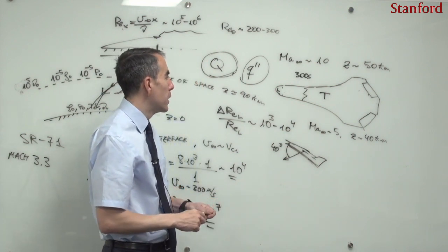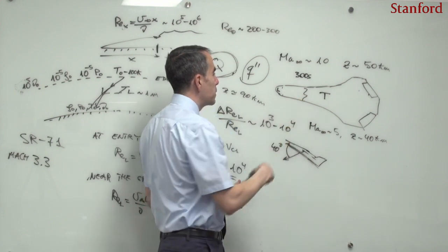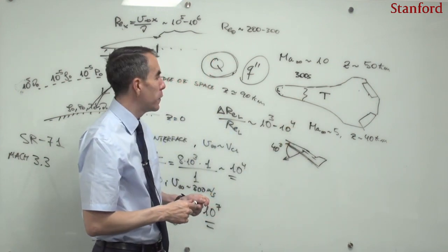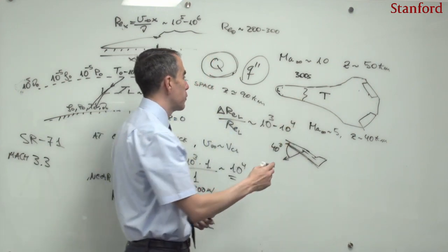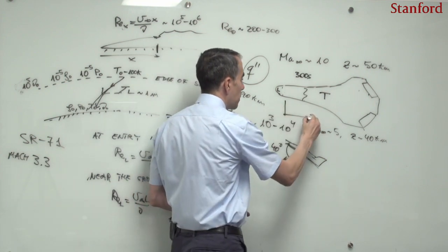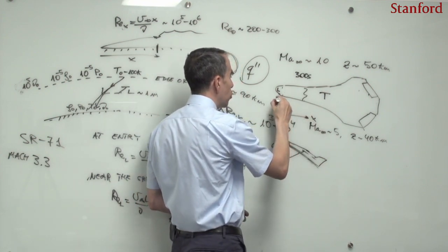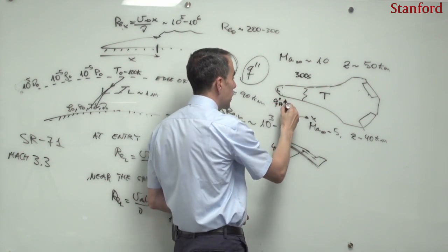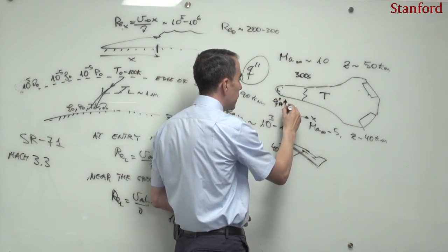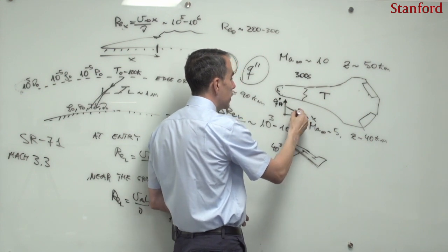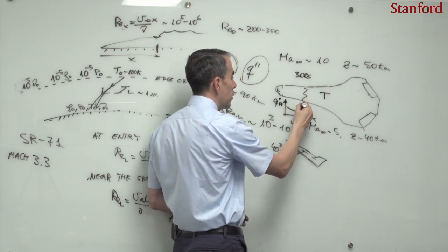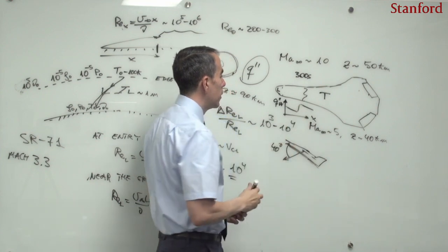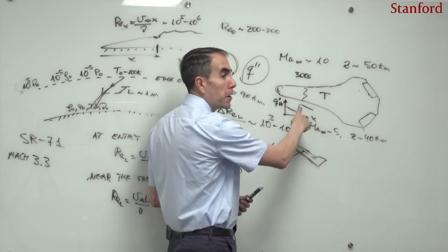Well, the physics of this process is kind of involved, right? So, for instance, if one plots here the streamwise coordinate x and here the Stanton number, or let's say the dimensionless heat flux, one would encounter that the dimensionless heat flux here would decrease, and then upon transition would increase, and depending on the method for transition, one will have a peak there or not.